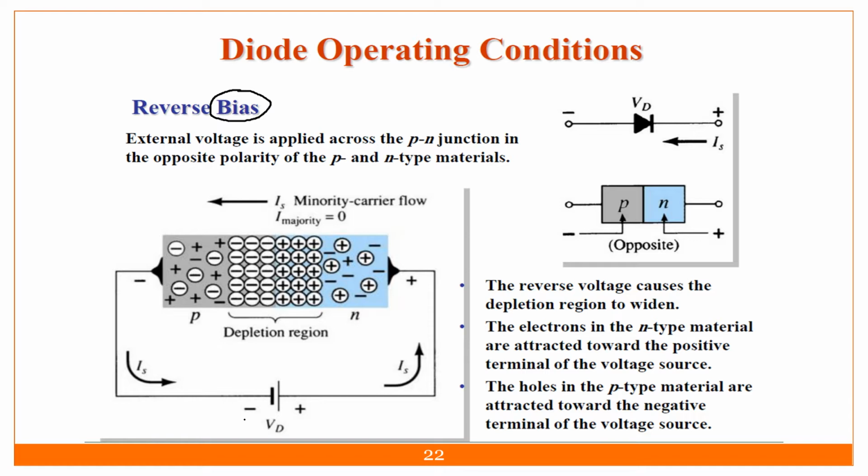But if you keep increasing the voltage, if you are giving -1 volt, -2, -3, -4, -5, -6, -7, at a certain voltage, near about 40 to 50 volts, what will happen? Whatever the current conduction is, it is due to the minority charge carriers. We know that the direction of current is opposite to the direction of electrons. So electrons are flowing in this direction, and the current flows in this direction, from positive to negative.